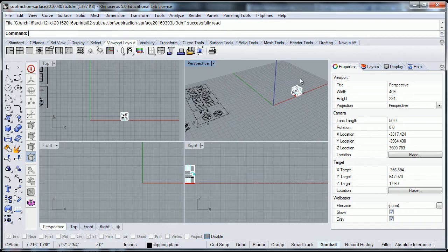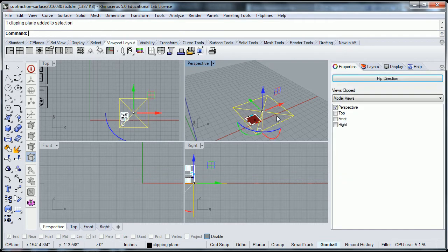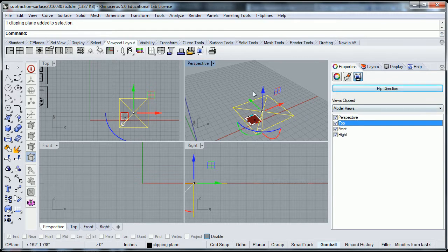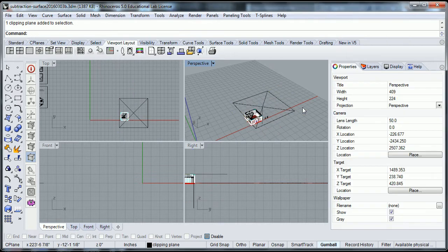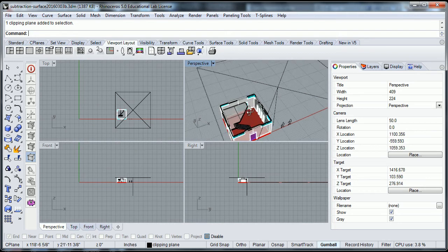So checking the Rhino model of that drawing, let's make a clipping plane, and I'll put it right there and bring it up to, what was it, 8 foot, 4 foot, so 12 foot, right? So that is my cut line right there.